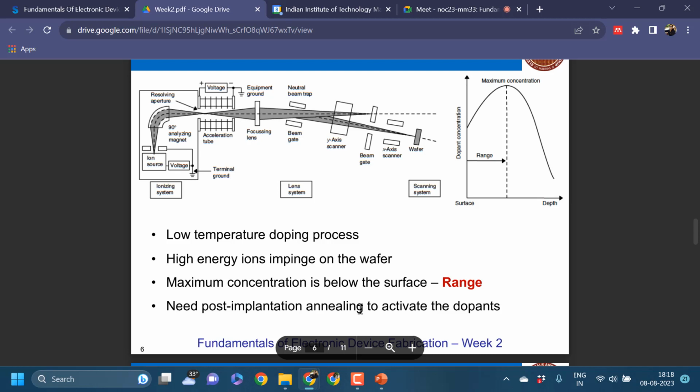To form junctions, change electrical properties. Yeah. You're also forming junctions. That is one correct answer. To control electronic properties. Yeah. So that is the main thing: to create junctions or to control the electronic properties, the conductivity or the potential required across the junction, etc. We need to do the doping process, and the doping process will be done using ion implantation as well as thermal diffusion.